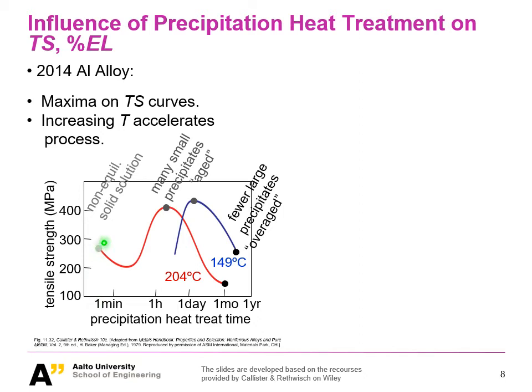This is where you don't do any heat treatment, and this is the non-equilibrium solid solution, of course. If we apply a little bit of time where you could have some diffusion, but the diffusion is not really significant, you don't have enough of your theta phase, and this will cause a slight decrease from the initial case.